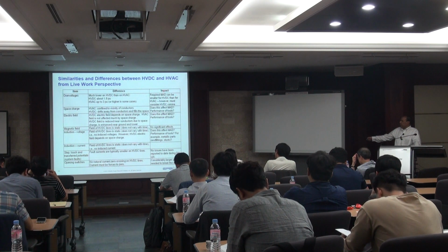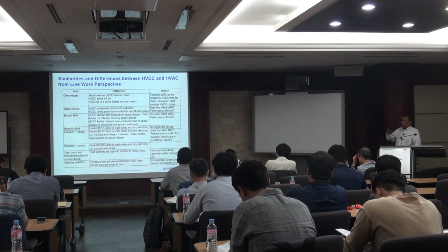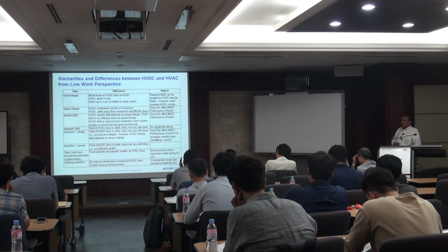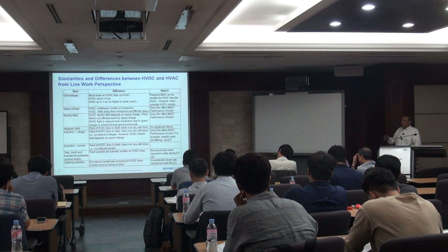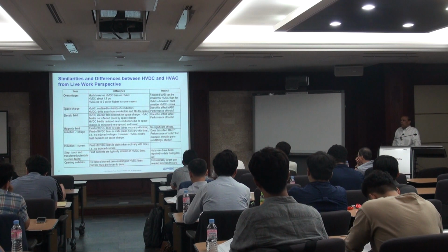At EPRI we are doing a lot of tests, energizing the lines for AC as well as DC, changing the configuration of the lines and changing the distance. We use what we call a bucket truck, where a person sits on the truck and changes an insulator, for example a failed insulator.